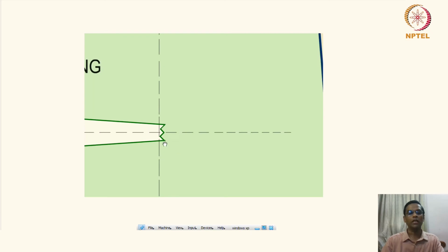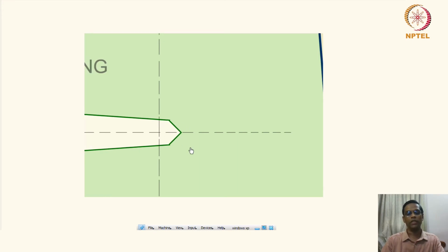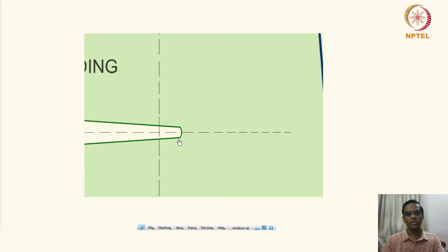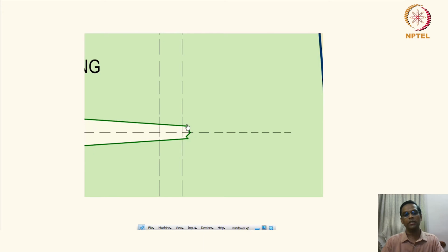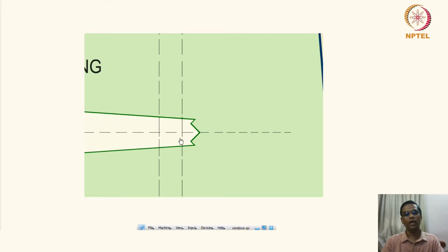So you can see that now it is unloading, and then the crack extends like this because of the plastic deformation, and then it becomes blunt because of the plastic zone. We will see later how this is really true. And then because of this, you can see that now a delta A increment has taken place, and then this reaction continues, opening and then closing.